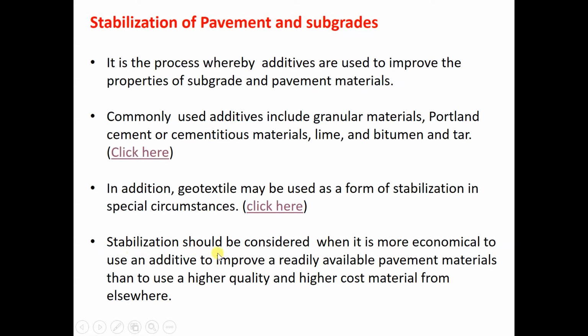Okay, stabilization should be considered when it's more economical to use an additive to improve the readily available pavement materials than to use a higher quality and higher cost material from elsewhere. So actually we need to look at the reason or the rationale for whether we need to stabilize the material.